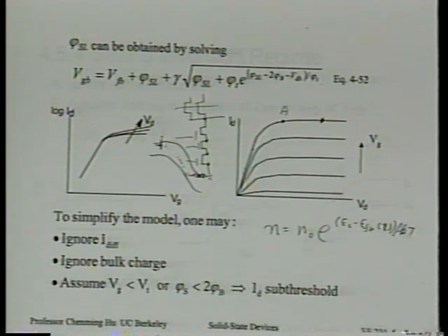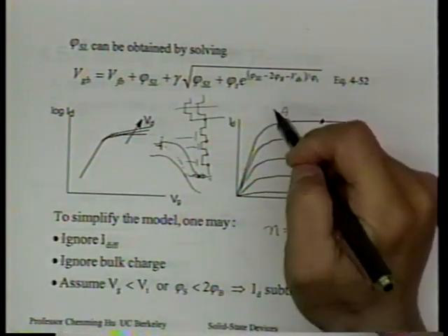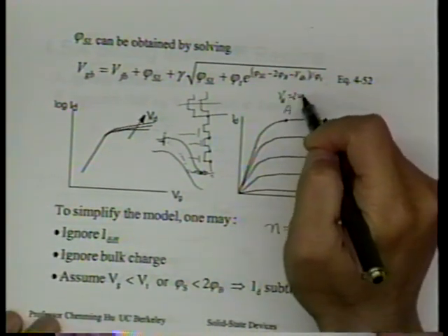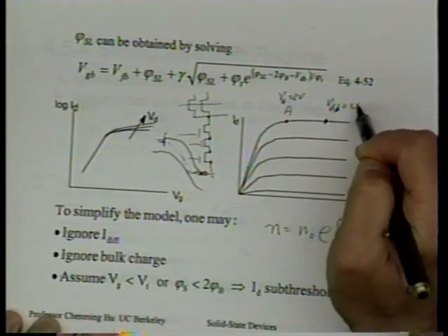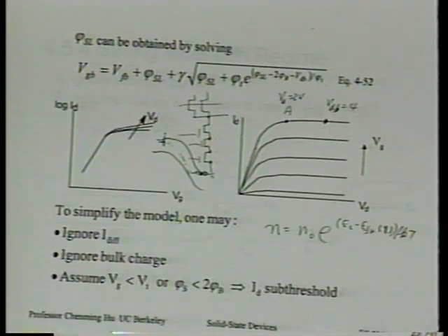I think it does not? I see. What would it do? If it saturates at VD equal to 2 volts, and I put VD equal to 4 volts, what will happen? Yeah, when the device is biased in the saturation region, then the Charge Sheet model at the drain end will fail. Is that right? Yeah. All right. So in this case, it's just available for the linear region. I see. All right. So I take your word for it.